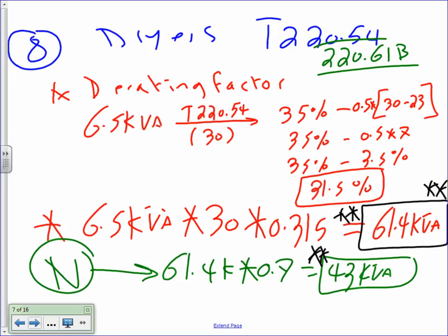Any comments, any questions about step number 8? Zach, makes sense? This is what you guys are doing for me for the load calculation. You're cutting it to 70%, not by 70%. You're multiplying by 70%. If you cut it by 70%, it's going to be gone down to like a 30. You are demanding it at 70%, meaning you're taking only 70% of it. You're using 70% of it. Okay, so that will be it.